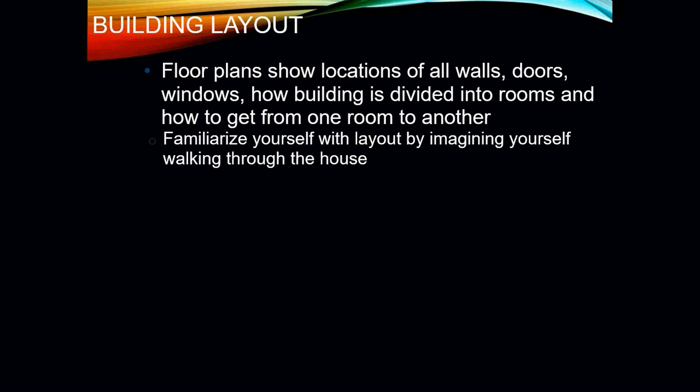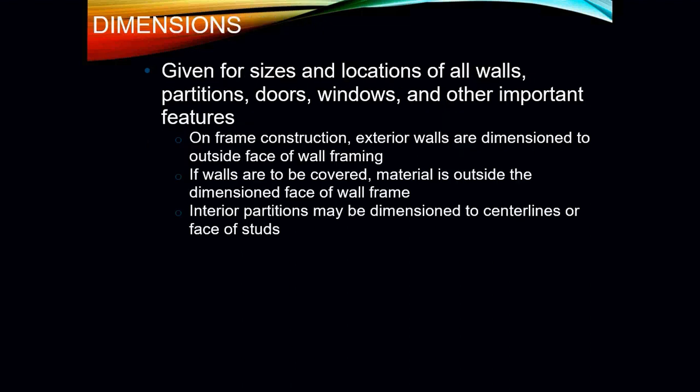So when you're on a job site, you're going to use the floor plan a lot. Okay, that gives you a lot of orientation of where your line sets may have to be run. It's going to show you where your duct work is going to have to go. In fact, in some cases even where an air handler is going to be placed. You can use the floor plan to give you an idea of where a lot of these things are going to actually be placed.